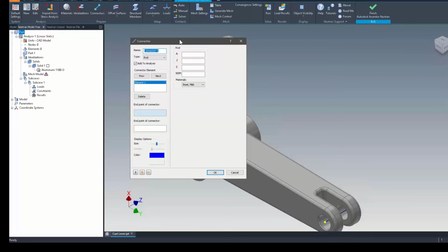Connectors can take the place of other pieces of model geometry. So typically you don't model and analyze bolts and nuts and connecting rods like that. In most cases, we already know what the structural limitations of a lot of those types of fasteners is, so we don't waste the time to model that into the analysis. Plus, it takes more math, and it can slightly shift the results a little bit, taking into account some of